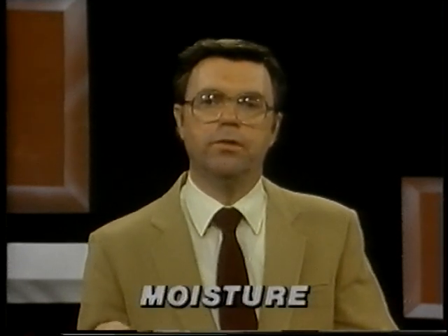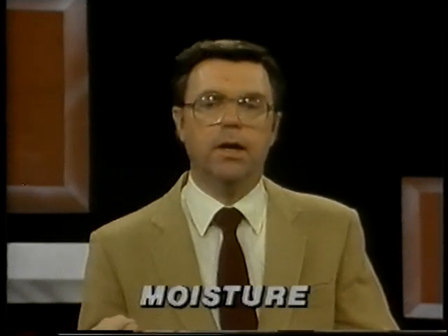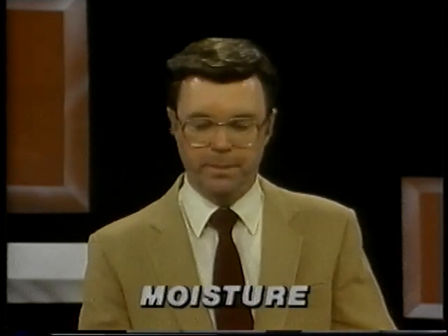What are some of the factors that affect atmospheric corrosion? Well, one of those is the moisture. What's the moisture level in the environment? And one of the things we find that's most critical in determining atmospheric corrosion rate is simply the time of wetness. If we expose panels outdoors around various sites in the country, one of the greatest correlations to corrosion rate is how long were the specimens wet. If you put them out in Arizona where it's dry and low humidity most of the time, the corrosion rate is very low. If you put them in a seaside environment where it's moist all the time and humid, the corrosion rate would be much higher.